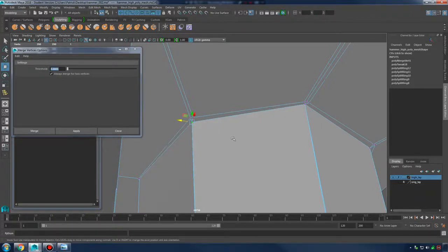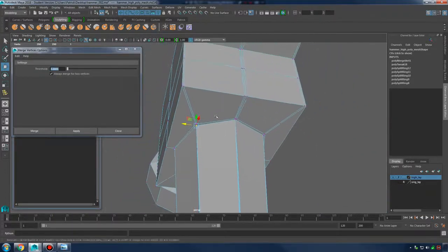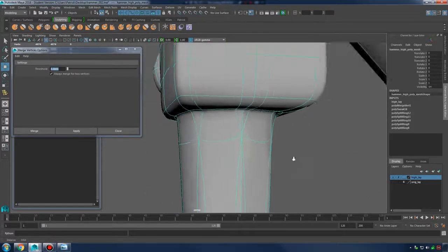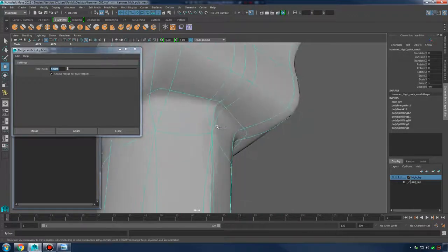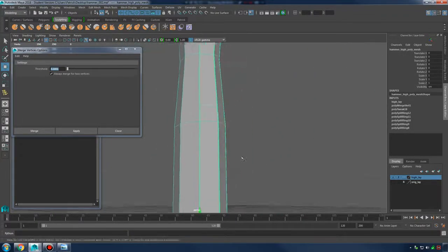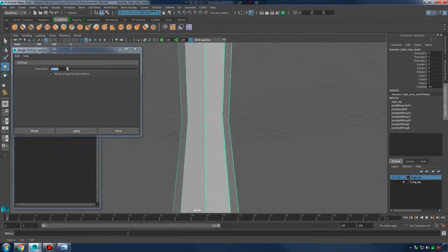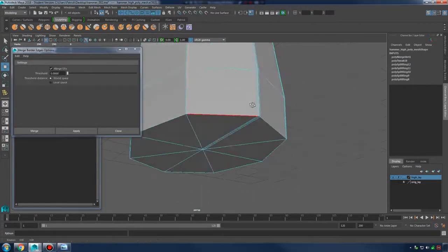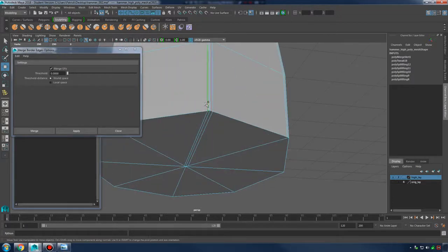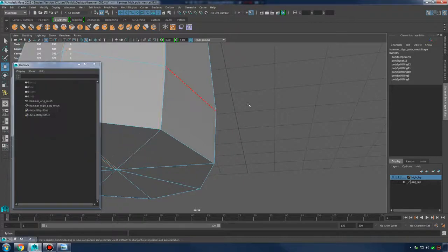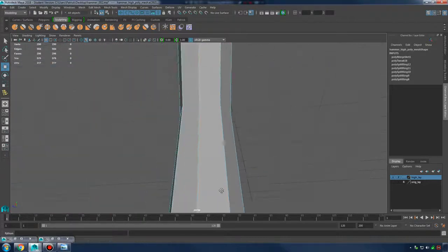I do one click, and I grab one vertice. Alright, surely that'll fix it then, right? No, that just made my hammer look weird. What we need to do now is get rid of these bottom edge loops. And tying off the edge loop here, I'll double click there, double click this, double click that. So I got these edge loops on my handle selected.